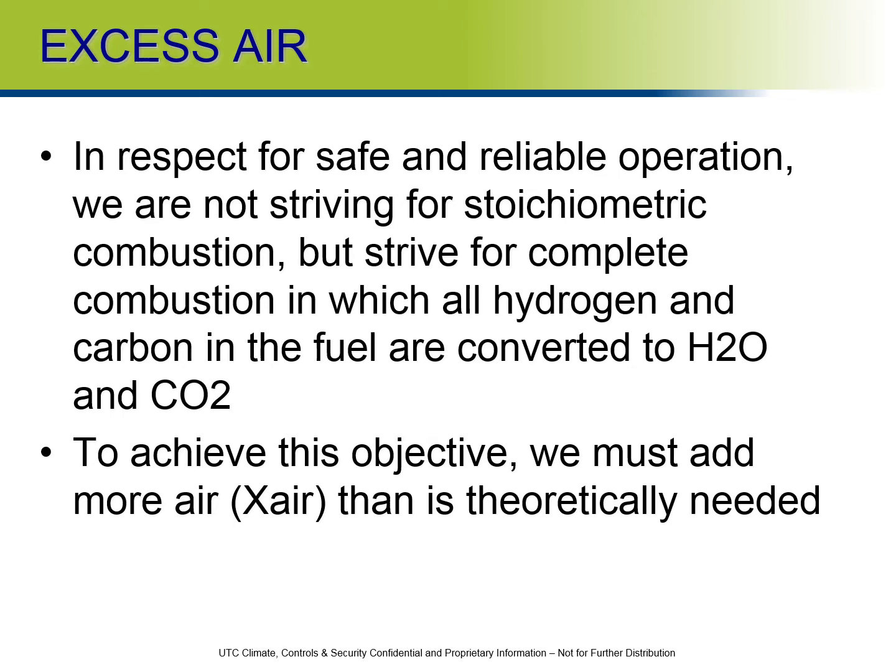Like I said in the last slide, in respect for safe and reliable operation of the equipment, we don't strive for stoichiometric combustion. We strive for complete combustion, in which all the hydrogen and carbon in the fuel are converted to H2O, water vapor, and carbon dioxide.